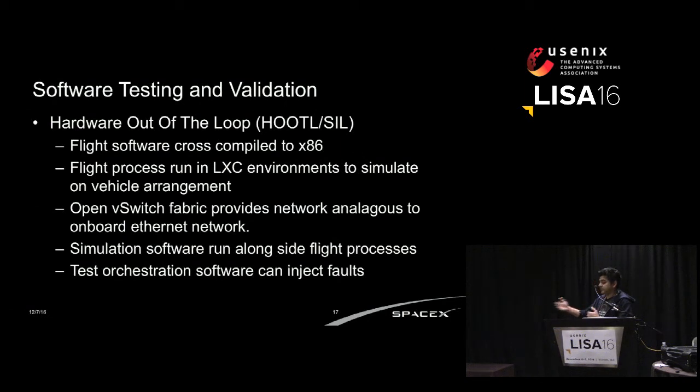Then our simulation side that is feeding inputs into the flight software runs alongside these containers and is basically hijacking the point at which data gets ingested from the data acquisition systems, from the sensors. And then the simulation side also accepts the outputs, like engine commands and various valve commands, and creates this overall simulation of what the vehicle will be doing in flight.